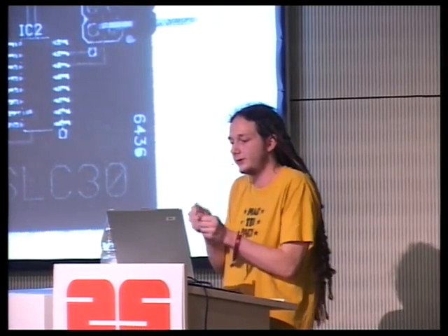If you glitch through it such that it never actually compares a byte, then it can never disable your access. And the way the code works, it first gives you access, and then it compares all of the bytes. And if any byte is wrong, it cuts out access. If 12 are right, it cuts out access 12 times. But if none of them are compared, then it never cuts out access. If only the first one is compared, then you only have to get the first one right. And this is in a loop, so falling out of the loop allows you to skip all of the rest of them without having to perform the glitch multiple times.